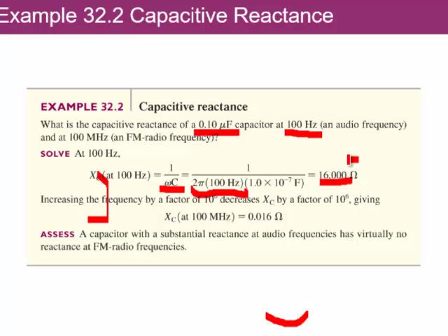Notice here the units are ohms, which is what's interesting about the capacitive reactance. There will be something similar for the inductors later. They are in units of ohms, and so they are very similar to resistors, except that, again, if you change the frequency, the omega, then this number will change as well.